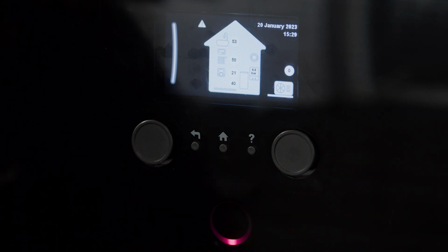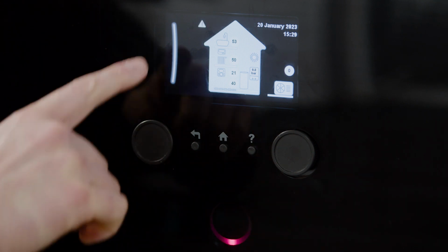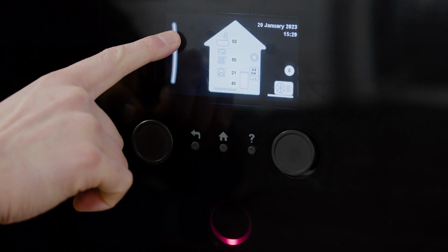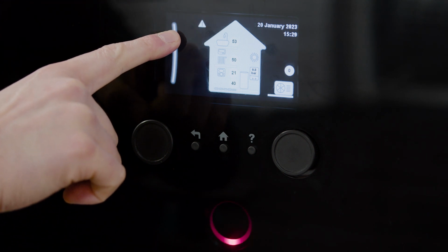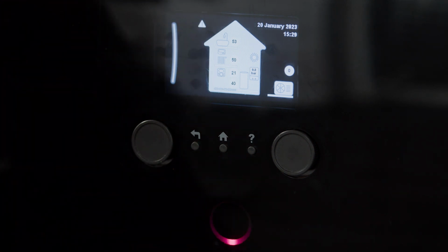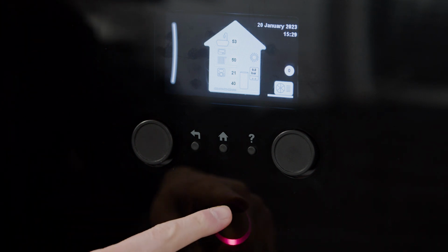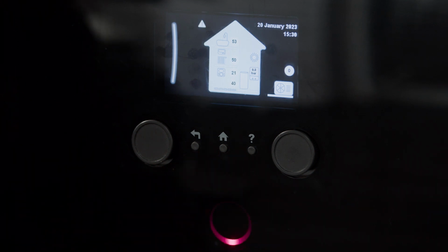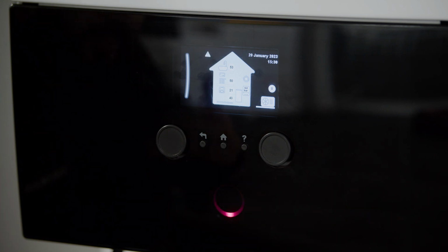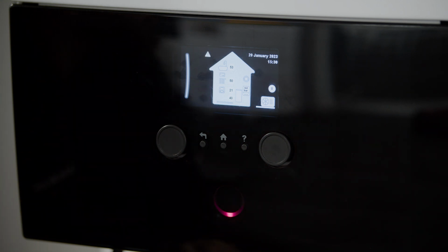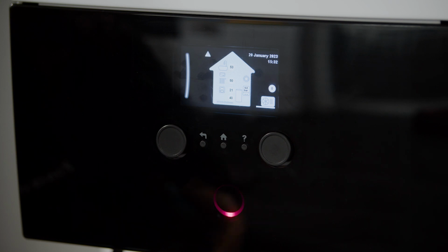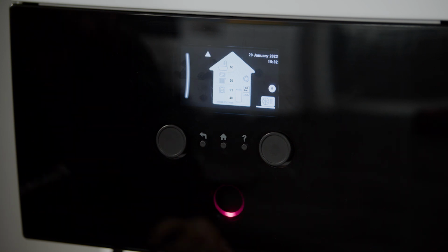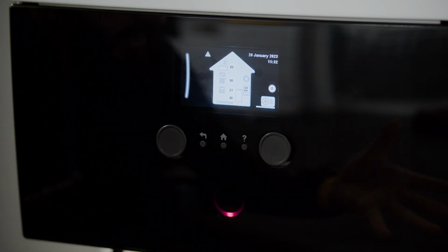If the system goes into fault, you will see the malfunction or error icon flashing on the screen, which is a triangle with an exclamation mark. You will also see the Daikin eye turn red. If you want, you can set the system in emergency mode. This means that the system will activate the backup heater for space heating operation or immersion heater within the tank for domestic hot water.